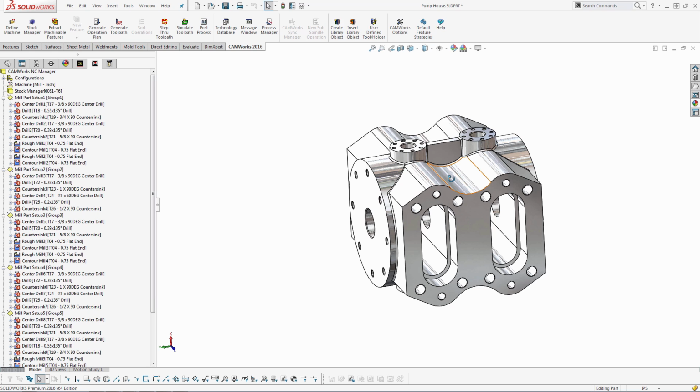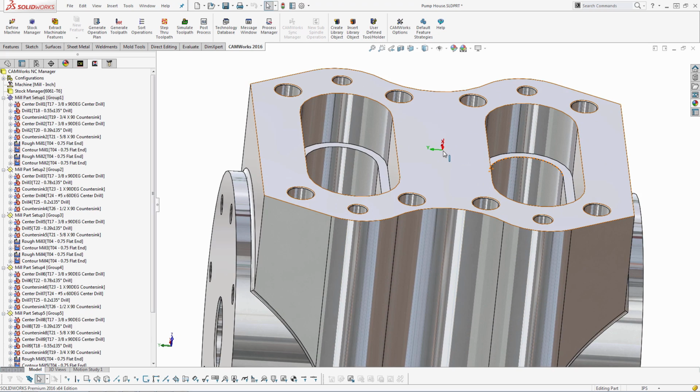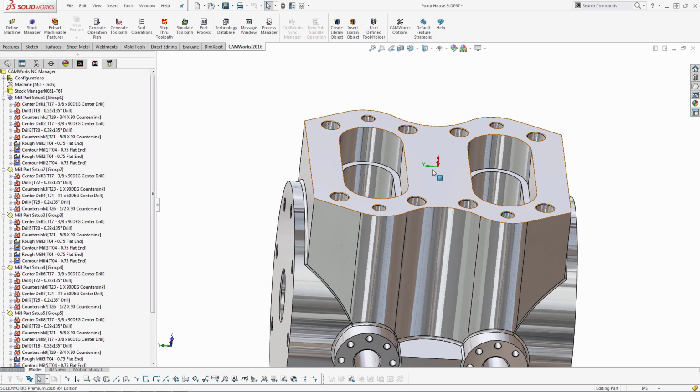Okay, that's basically it. Beyond making sure that our part zeros are in the correct spot, this is all that there is left to do. When it comes time to doing the part zeros, what we'd want to make sure is that they're in the same spot on all different setups. So on this particular part 0, we're in the top center of the model. We're going to want to make sure that that corresponds to every single setup around the block.